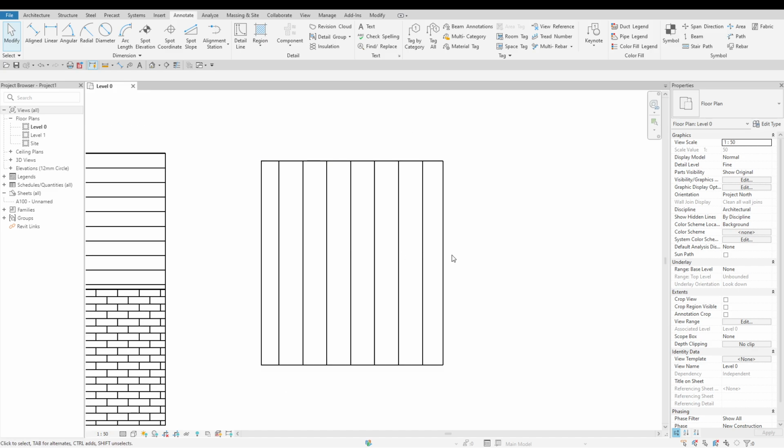On the other hand, Revit also allows you to create new fill patterns, ranging from simple, predefined types to fully customized project-specific designs. A basic fill pattern typically consists of evenly spaced lines, either parallel or orthogonal. Common examples include diagonal crosshatch, vertical siding, or brickwork patterns. These are ideal for representing generic materials or drafting symbols.